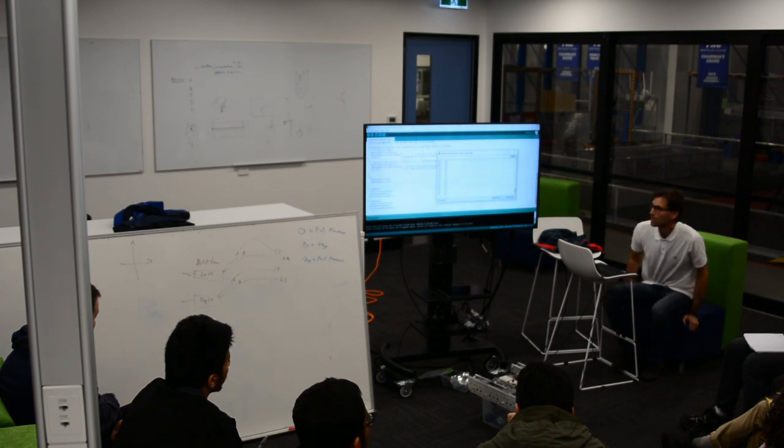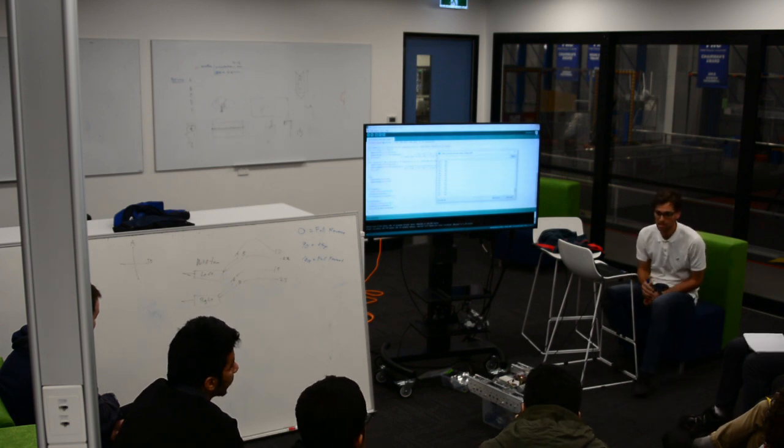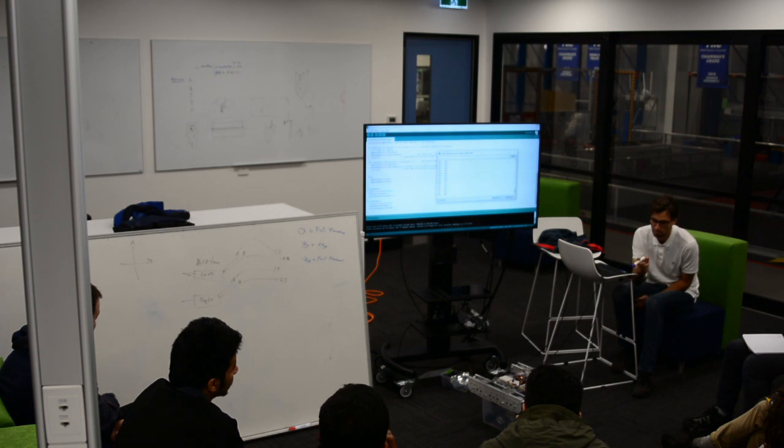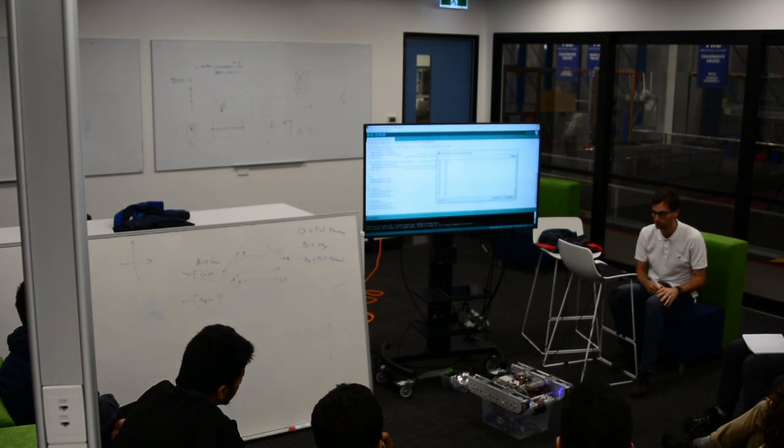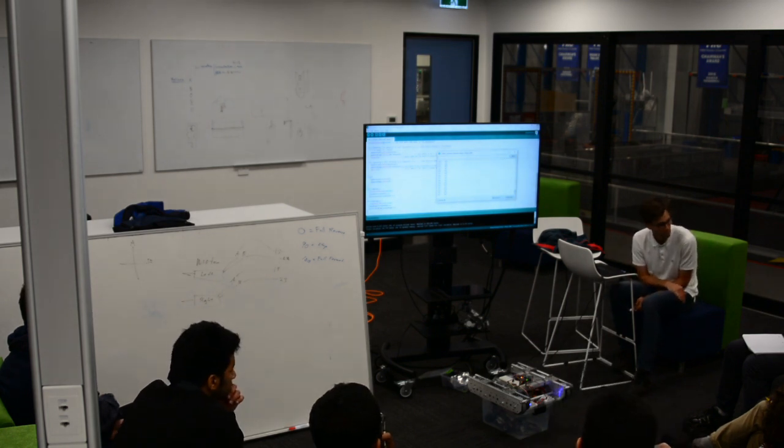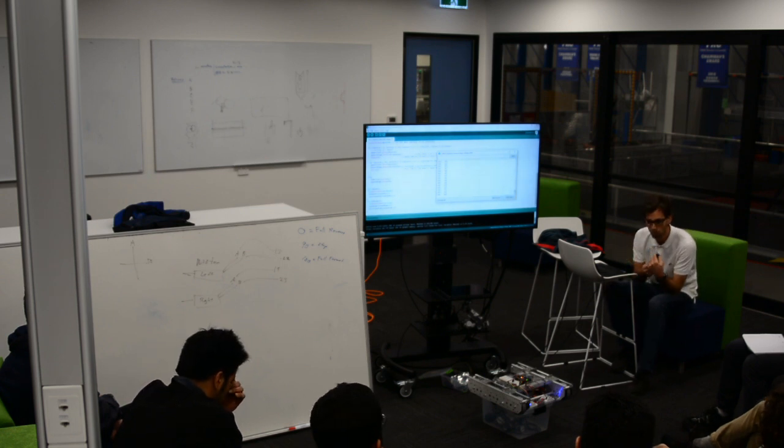There we go. Okay. I noticed they're not exactly even, so does that mean it's kind of like slipping? Yeah, what we're going to see is that one side of this robot has more friction than the other. So if you increase the throttle, one will start moving before the other one, because one has a lot more friction on it. Is that by design? No, that's just shoddy build quality. You could put some work into it, and I think it's not a bad thing to think about where this friction is coming from.